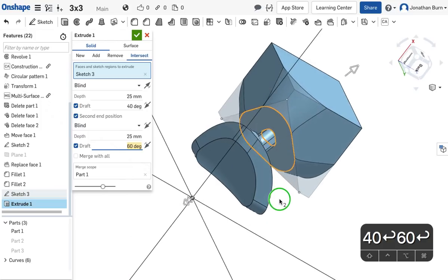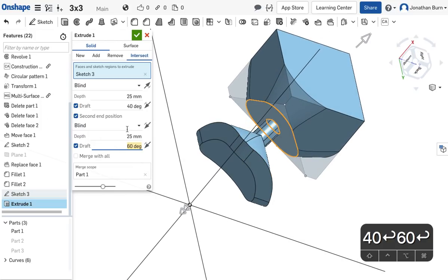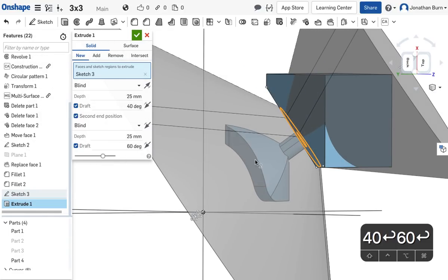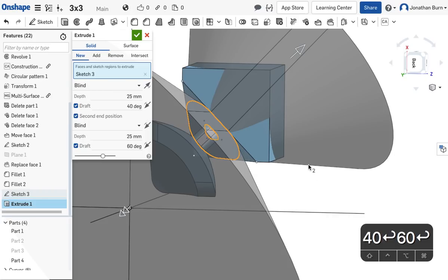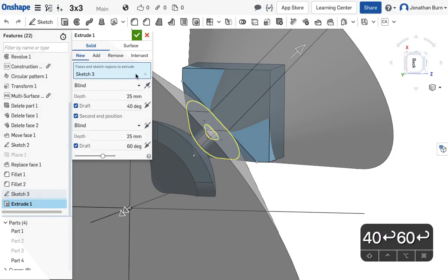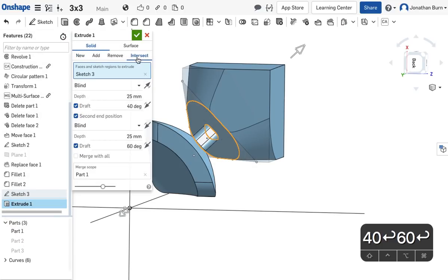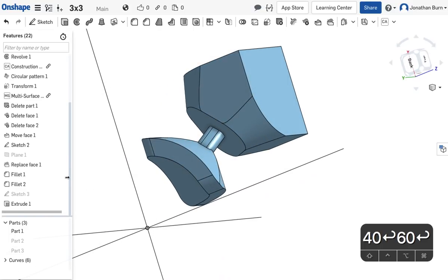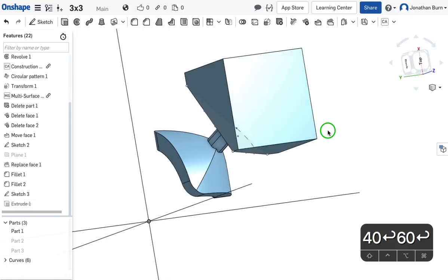There you go. So basically what I did, I'll show you what the surface looks like now. I just created something, and so all of this foot here is included. Oh, whoops. I want to make sure it's on intersect. There you go. Another way that we could have done this, let me just right click on this extrude and say suppress. That'll just sort of undo it.